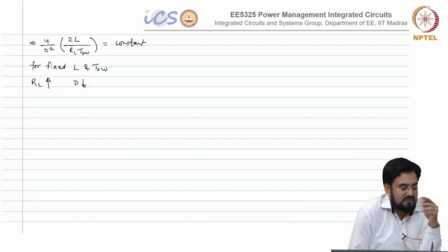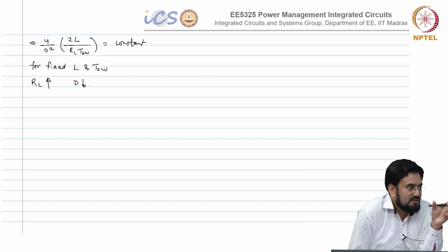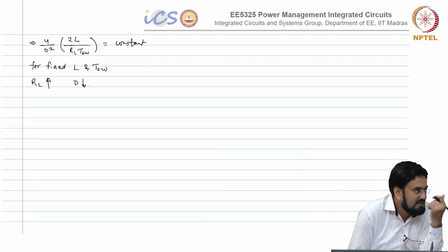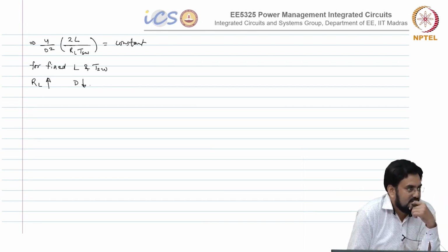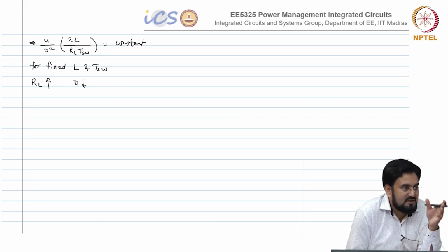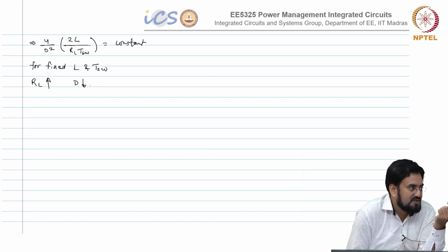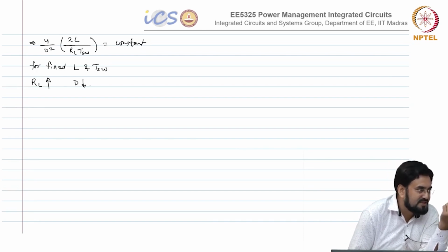Okay. So, for the same V out by V in ratio, if you are getting some duty cycle in the CCM, when it enters into the DCM, the duty cycle will become a function of your load current. In fact, in CCM also it is a function of load current, because your conduction losses will increase. You remember the delta D term we required, but that will be very small, maybe 1% or so.